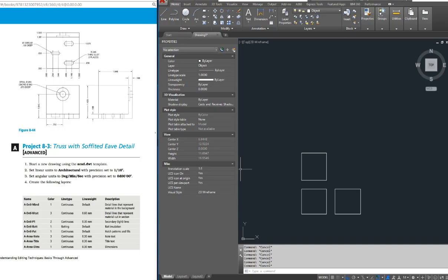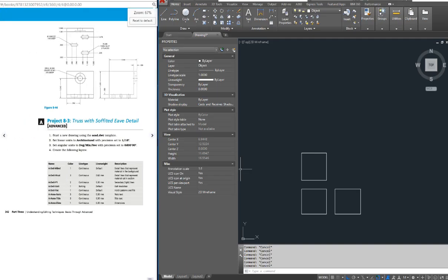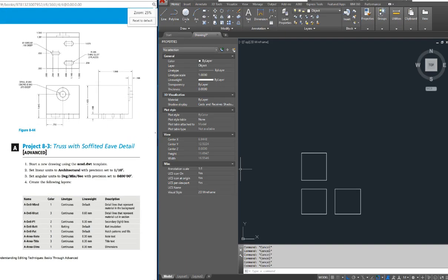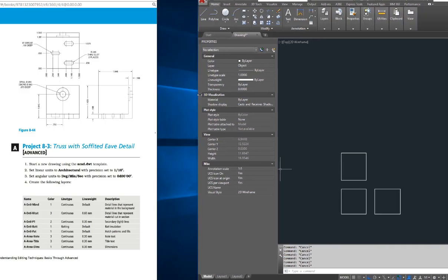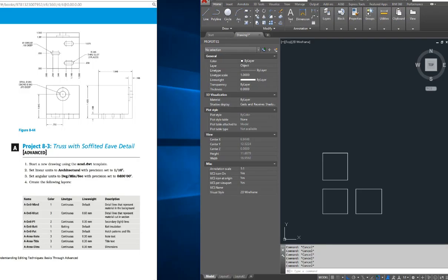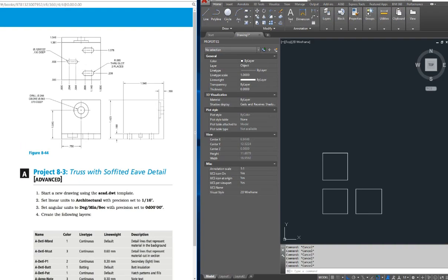And probably the easiest way to do that is going to be, now this is datum dimensioned, so it's a little bit different than something you might have seen before, but it's no big deal. It has a 0 reference, and it gives you a distance from that 0 reference.